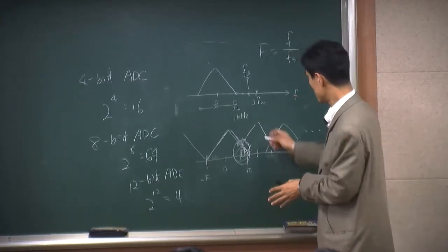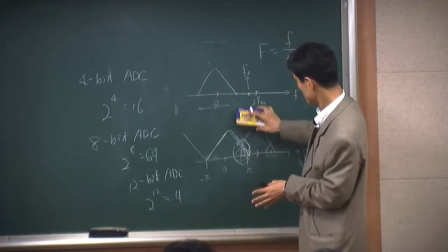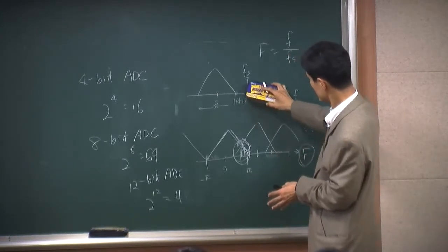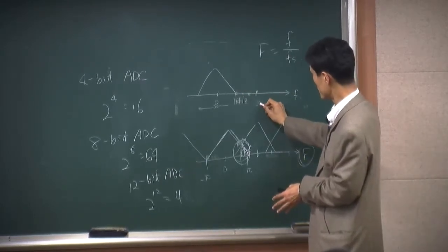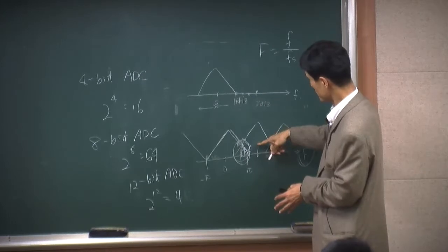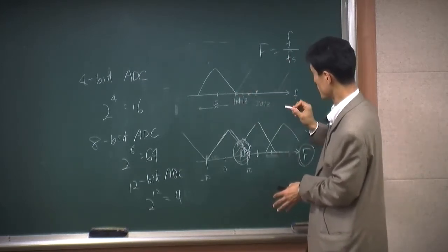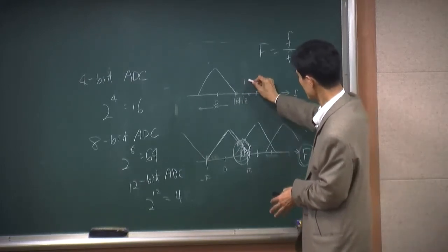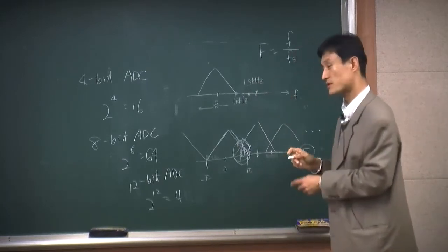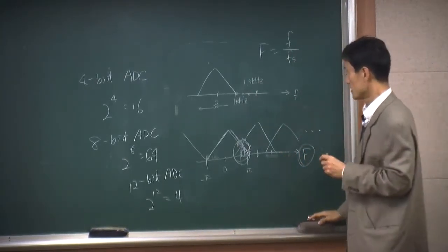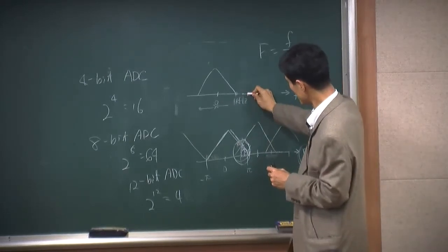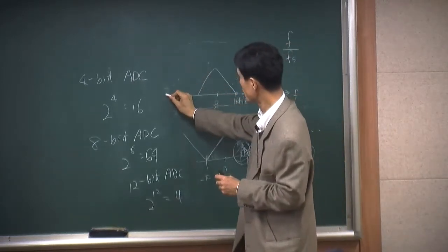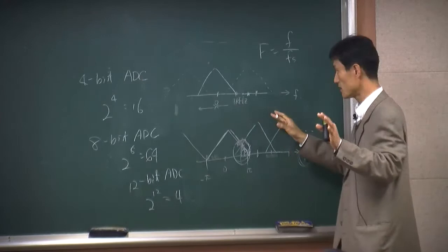Okay, something like, for example, right? Let me look at it here. For example, here's a 1 kilohertz. So if you use sampling frequency as a 2 kilohertz, right, and then sampling, then it looks like this way, which is good. But if you use, let's say 1.5 kilohertz as your sampling frequency, in that case it's undersampling, what happens is, for this 1.5 kilohertz, you're going to have another image. We call this an image, right? You have image, every image in 2 pi.